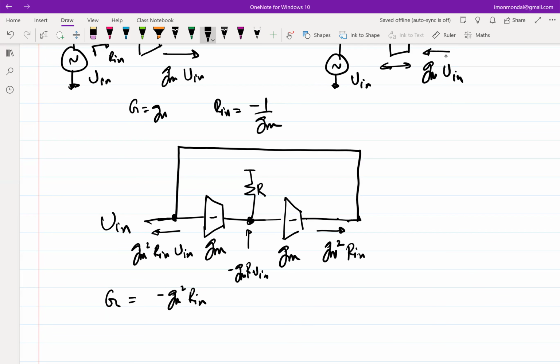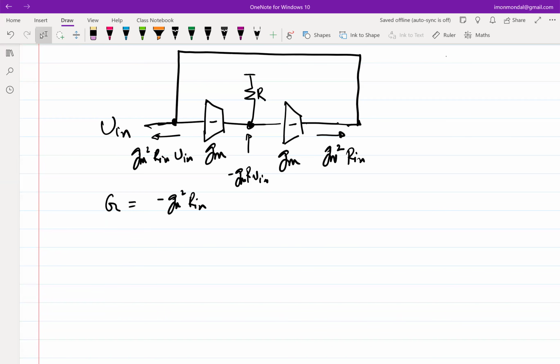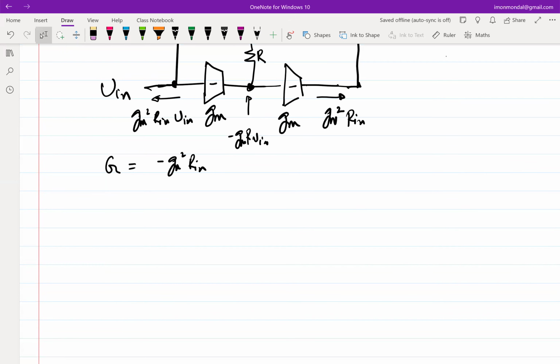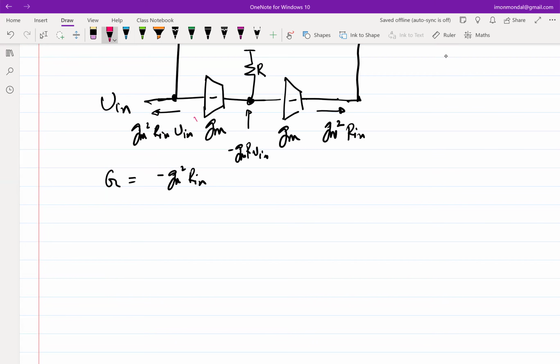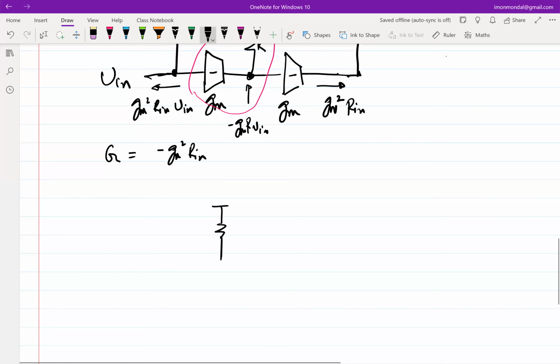Yeah. So now, if I replace these cute little boxes with transistors, you'll be able to figure out a configuration which I'm sure you have seen in some format or the other. So let's do that. Let's say the first guy is a common source amplifier. I put it in this format. I'm not showing biasing and all, so assume biasing is present.